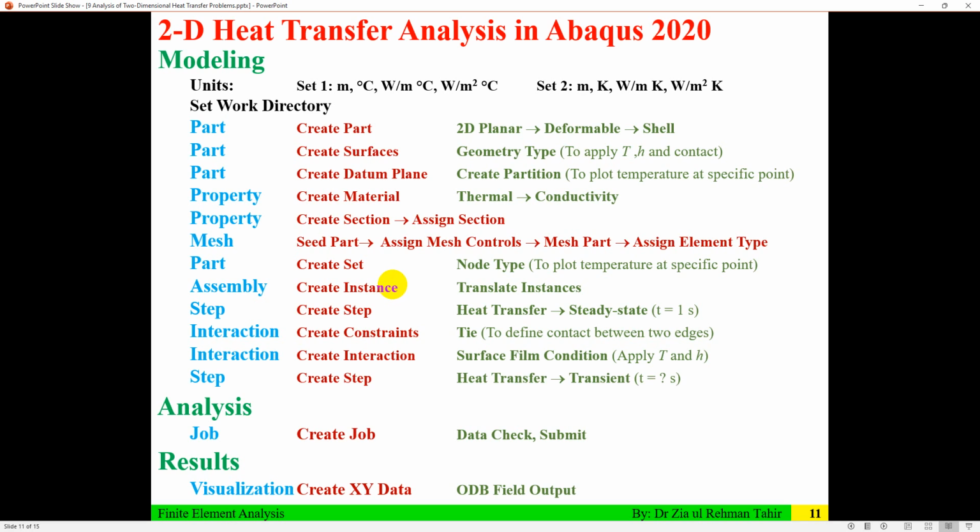And for transient state, it is easy if you first check everything using steady state condition. For that steady state condition, whatever you get, take as a reference. And once it is running for the steady state, then change the step to transient, and then check the time, so that you will get results closely similar to the steady state.